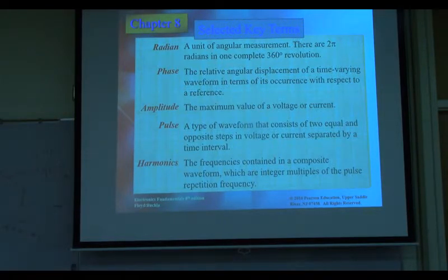So you may wonder why we have this harmonic noise. It's because the design is not perfect. You have a non-linear device inside. For example, if you have a diode inside, then you are definitely going to get a second order harmonic, 120. If this is very serious but your application needs only the fundamental, then you are going to use a filter.